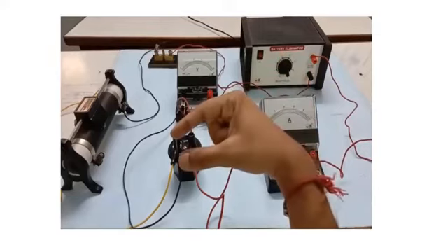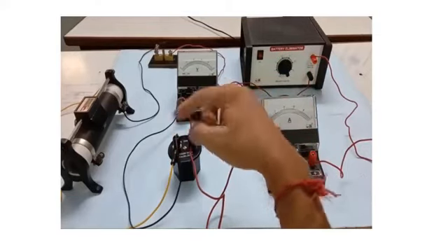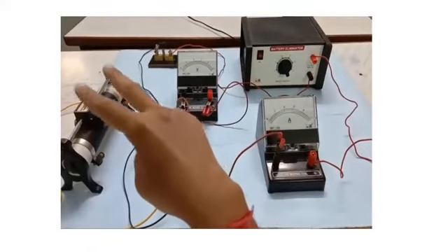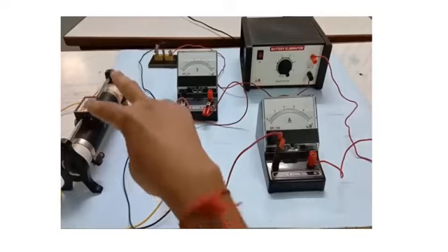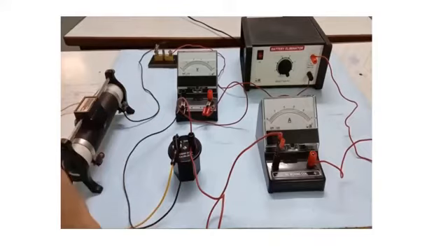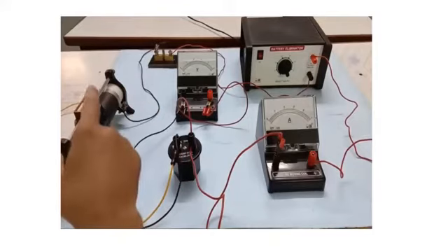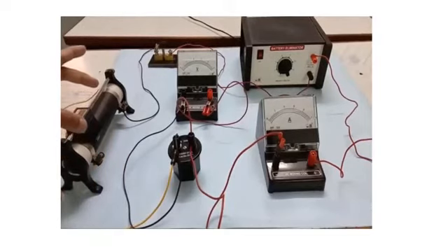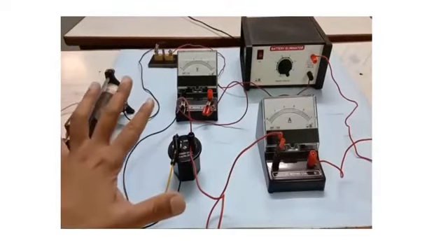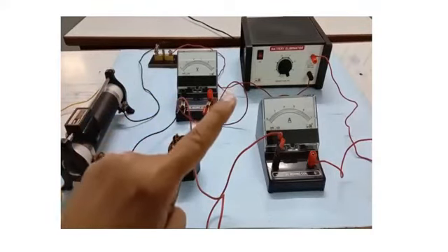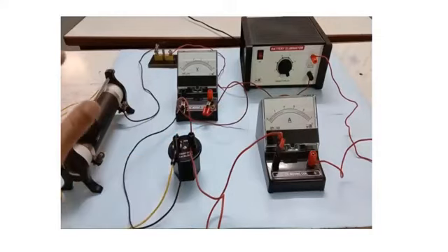So to start with, we have to switch on the battery. When you switch on the battery, we can see that the needle will be moving, and the needles of the voltmeter and the ammeter, very carefully you have to find what reading it is giving. So when you increase or decrease the value of the resistance from the rheostat, the V or I from the voltmeter or the ammeter will change. So how to measure that?